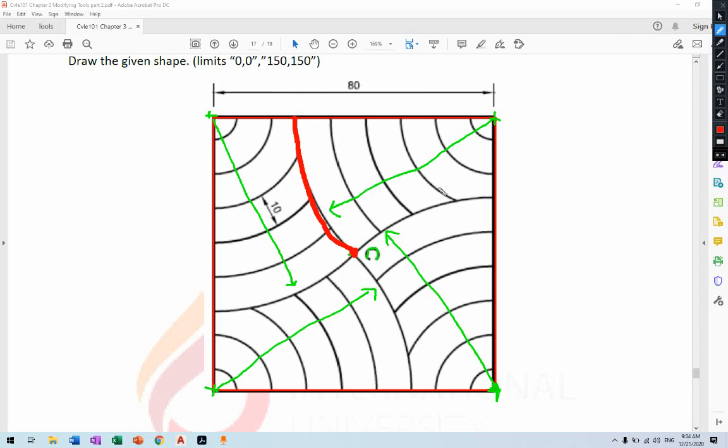For example, this is for this part, and if I do this one, they are connecting at the center. So can we get the center of this shape? Yes, I can get the center of the shape, and we can use that center to draw the four circles. Then from there we can simply use offsetting inward like this, or for example here inward, offsetting till we get back.